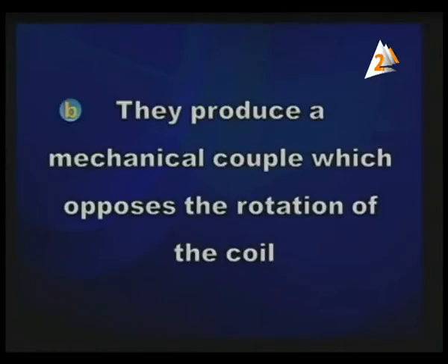Hair springs carry the current to and from the coil. They lead the current in and out of the coil. Once again, hair springs carry the current to and from the coil. They produce a mechanical couple which opposes the rotation of the coil.